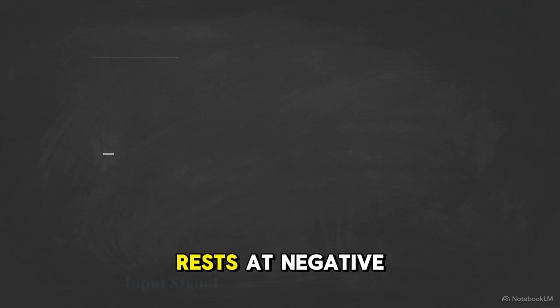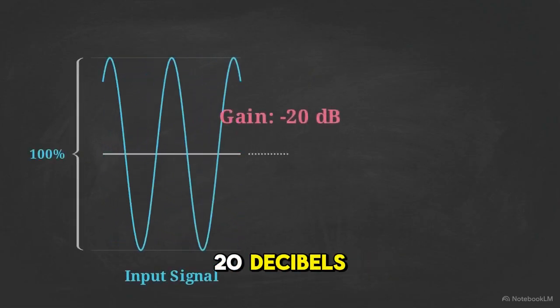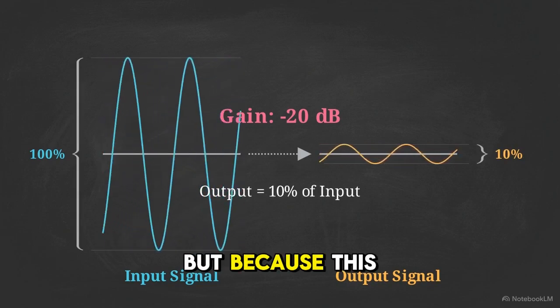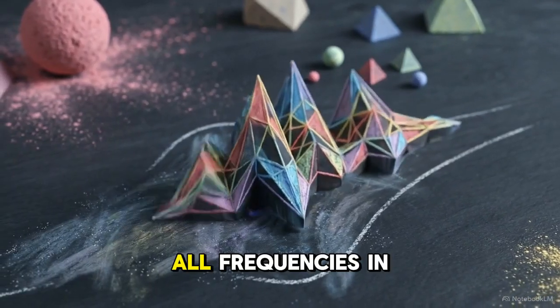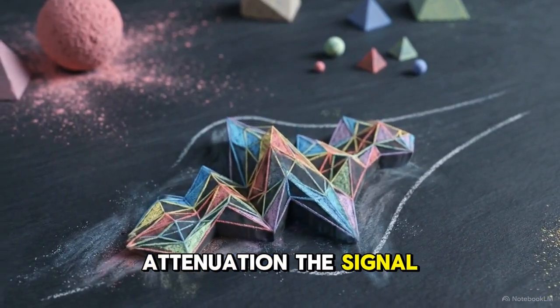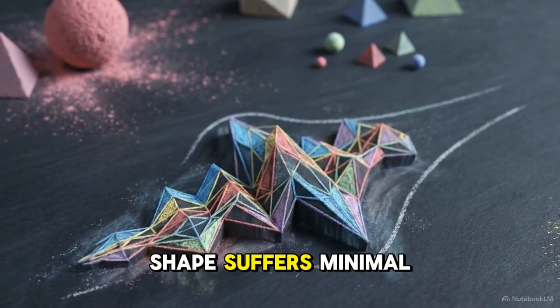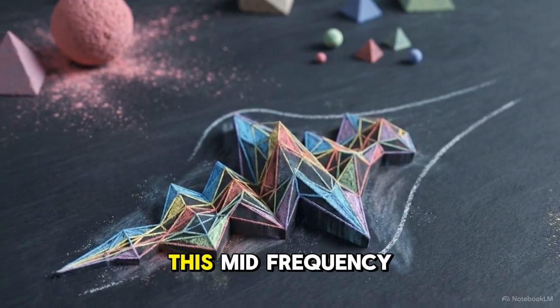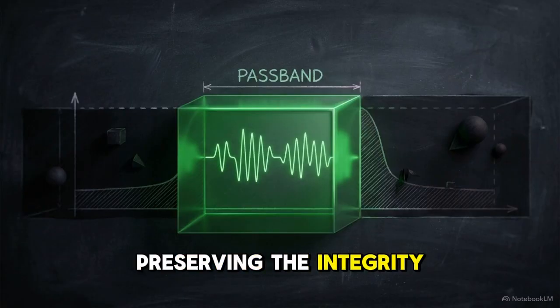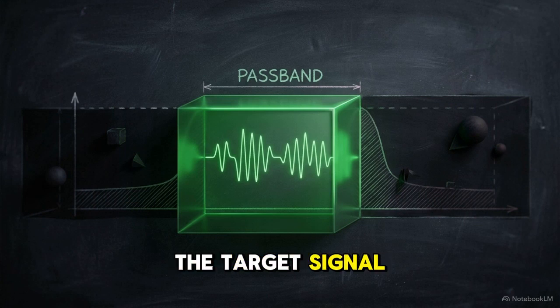The amplitude here rests at -20 decibels, meaning the output is reduced to 10% of the input. But because this gain is flat, all frequencies in this band experience identical attenuation. The signal shrinks, but its core shape suffers minimal distortion. This mid-frequency plateau functions as the passband, preserving the integrity and waveform of the target signal.